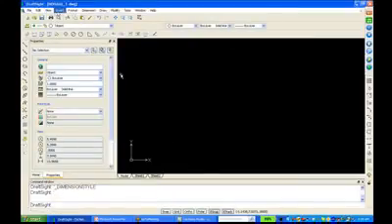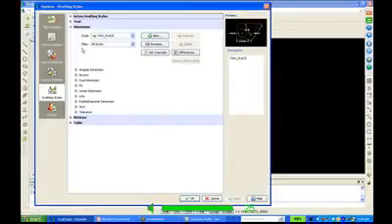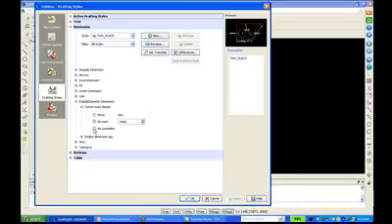Actually, let me see, format, dimension style. If I need to make a change, right now I'm in the 2 places. I'm going to go into my radial, my center mark display, and we'll create it as a center line. And you see the difference in the preview. The center mark is just a tick. The center line is the tick with the line on it. I'm going to apply that.